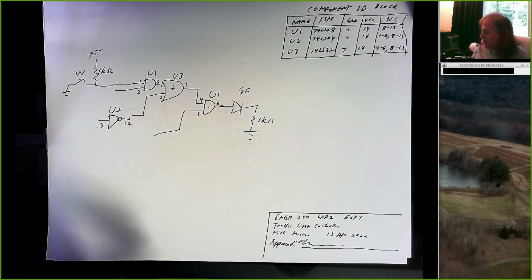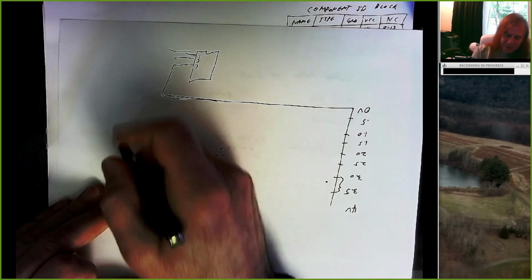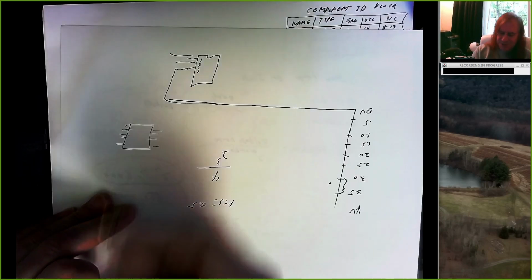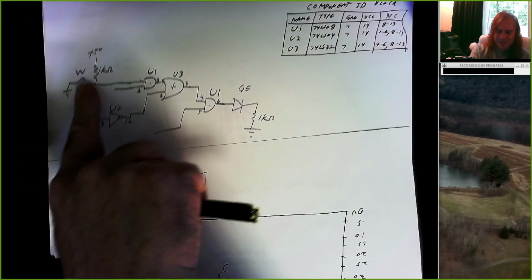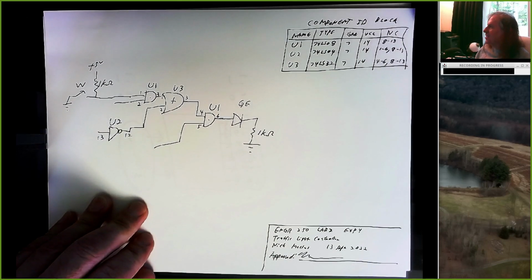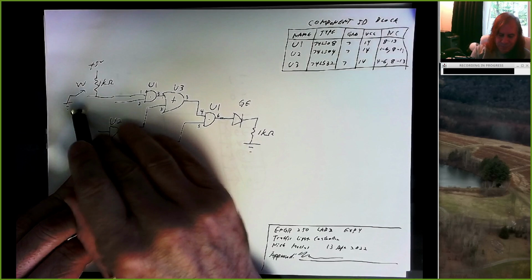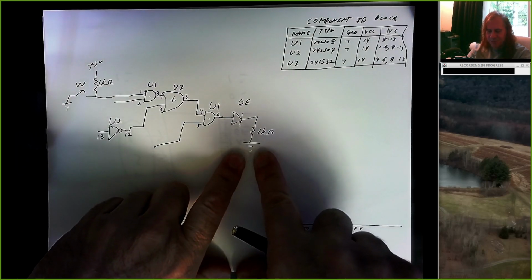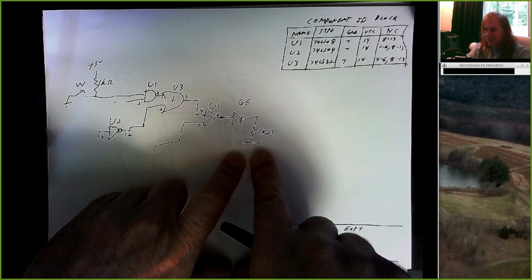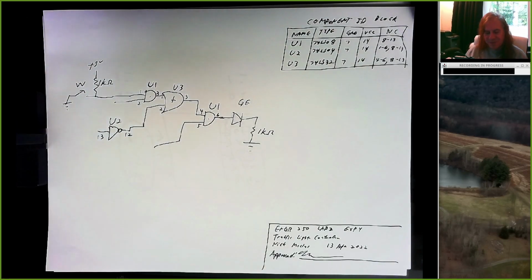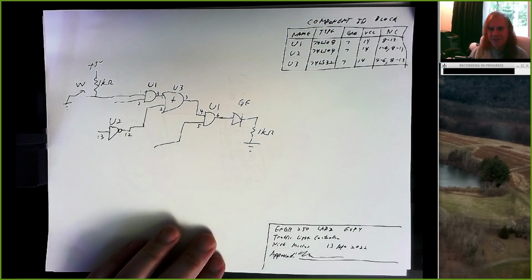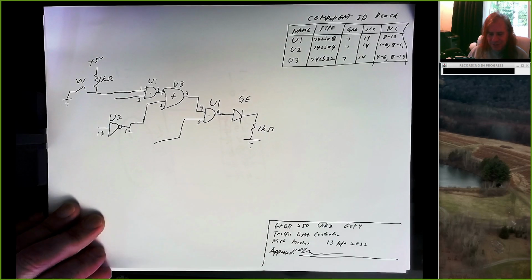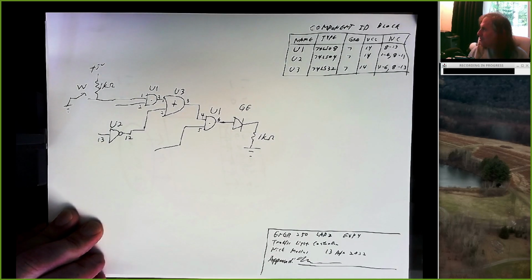Same thing with the switches. Don't draw a little switch block like this and assume that the person understands what that means. Use this little standard switch symbol, just an arrow hanging in the air, that connects this end to that end. For ground, you can use this symbol, just 3 smaller horizontal bars, one under the other. That's a standard symbol for ground. For 5 volts, you can just label positive 5 volts. And I think everything else is stuff you've already been drawing back through 120.